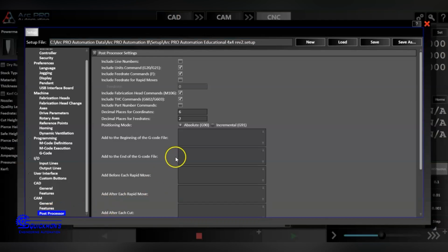Normally we tell you to input M30 at the end of every G code where you can have it automatically go to that parking position, but at times it's a little bit easier to just let the machine do its thing, and then once it stops you can just click a button and that button commands it to go to a position. So with that being said, we're going to go on the left hand menu again.